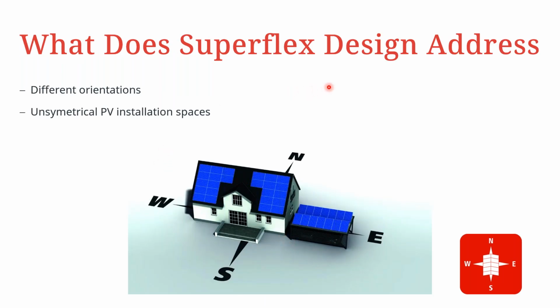So what does the Superflex design address? It addresses different orientations as well as unsymmetric PV installation spaces. So it allows you to orientate on one, so this is for different orientations, as well as your unsymmetric PV installation. So you can have much greater input on PV1, for example, or PV2, and then have another separate string on MPPT2.